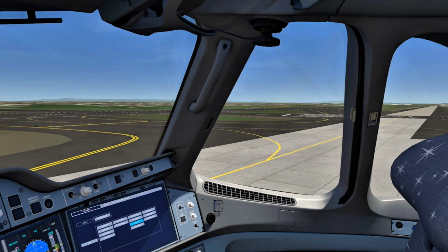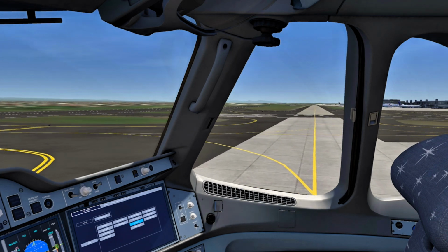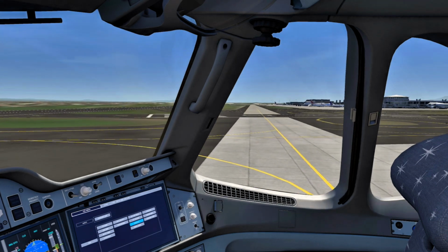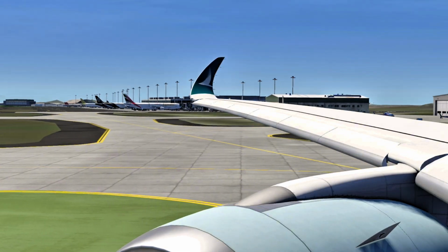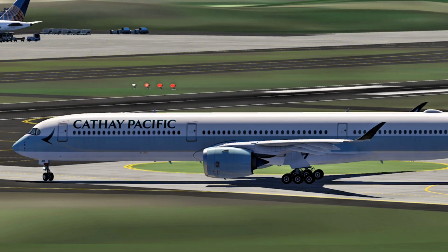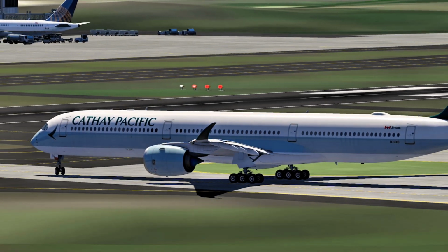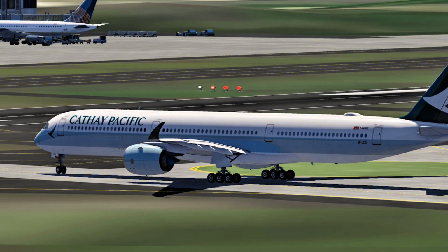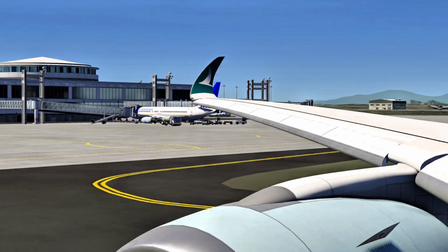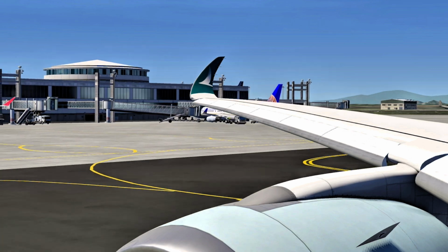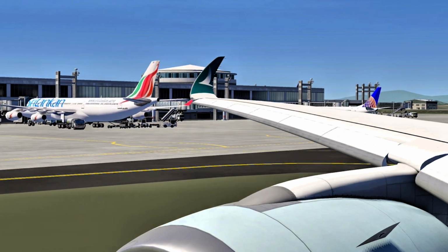Just to remind you, I'm used to the Airbus A320 that carries about 160 passengers. This thing carries 400. This plane is big. Turns like this are tricky, you got to be careful not to turn quickly but smoothly and gently glide that nose wheel, or else the aircraft's momentum will just continue pushing the nose wheel forward instead of actually turning the plane. That's Manila Airport's Terminal 2 by the way. Just don't mind the planes, it should be all Philippine Airlines jets there.